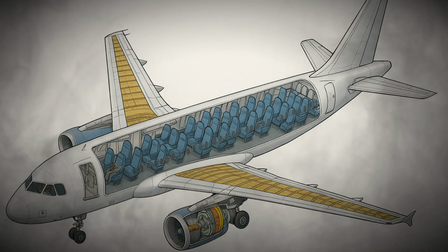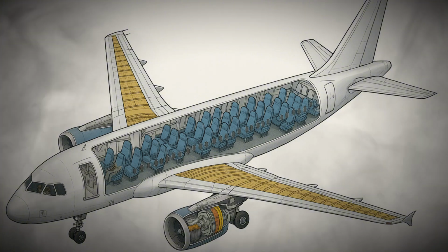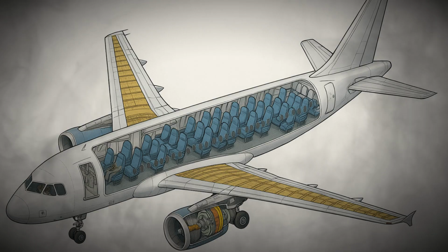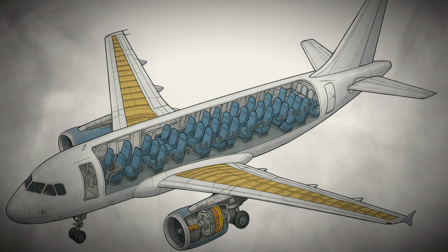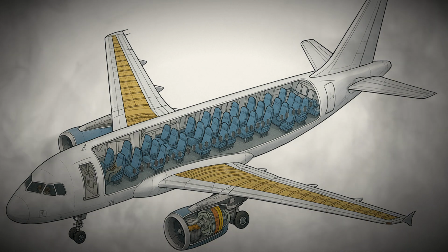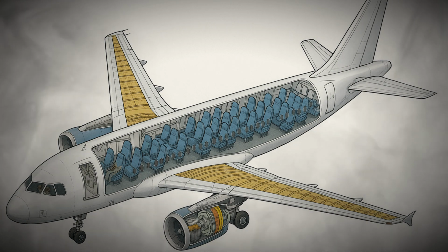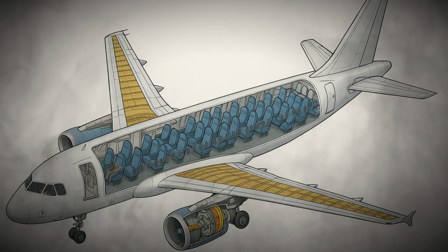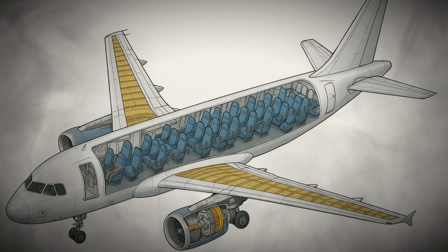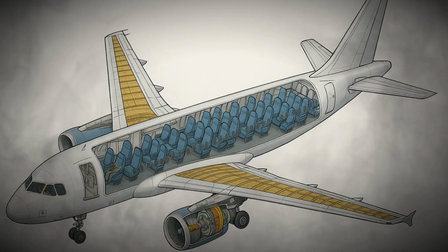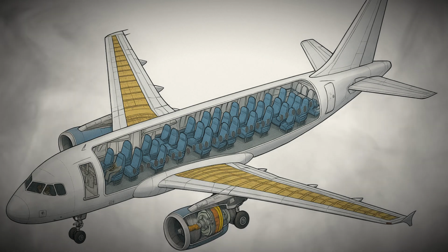As the airplane descends, flaps are extended in stages to increase lift at lower speeds and maintain control while slowing down. The landing gear is deployed, creating drag, but providing the means to touch down safely. Speed is managed carefully, with reference to VREF, the landing reference speed, calculated based on aircraft weight and configuration. Too much speed results in a longer landing distance, while too little risks stalling.